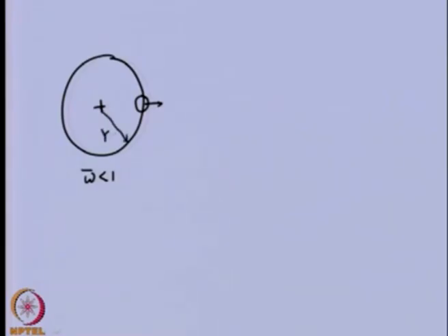Earlier we have seen the whirling of the shaft about its bearing axis, and when we are operating below the critical speed, that is frequency ratio 1, the unbalanced force is toward the outward direction, and this is the amplitude y which we talked about in the previous analysis.